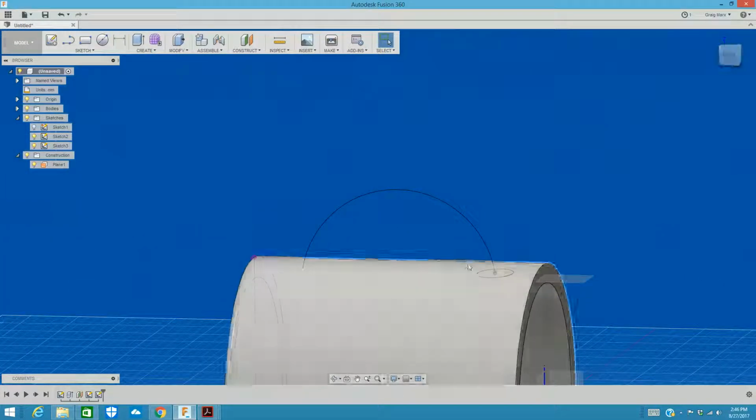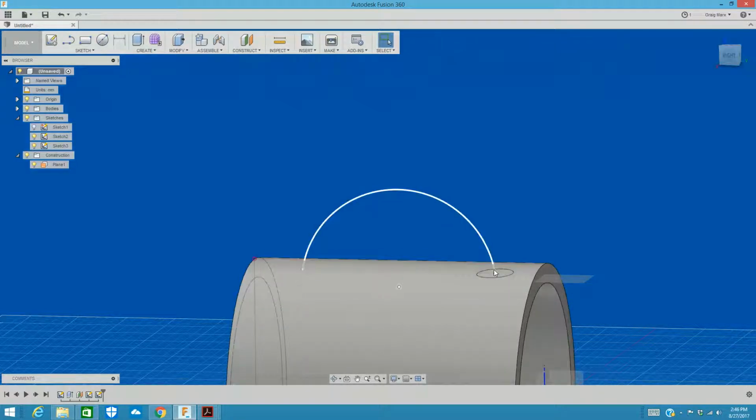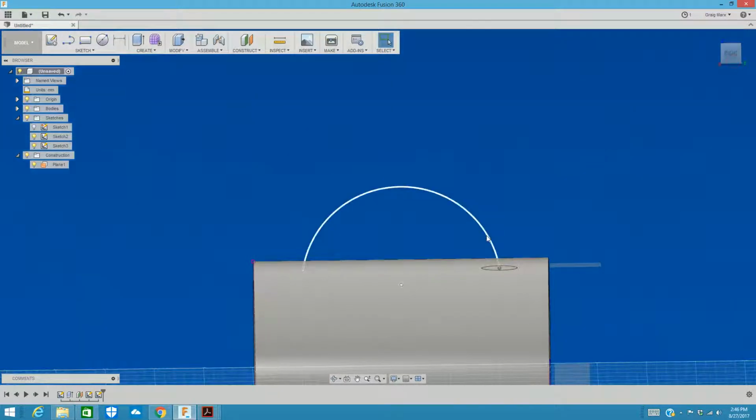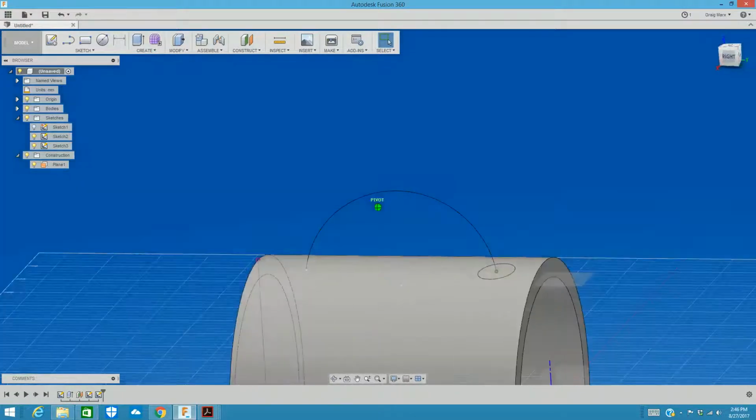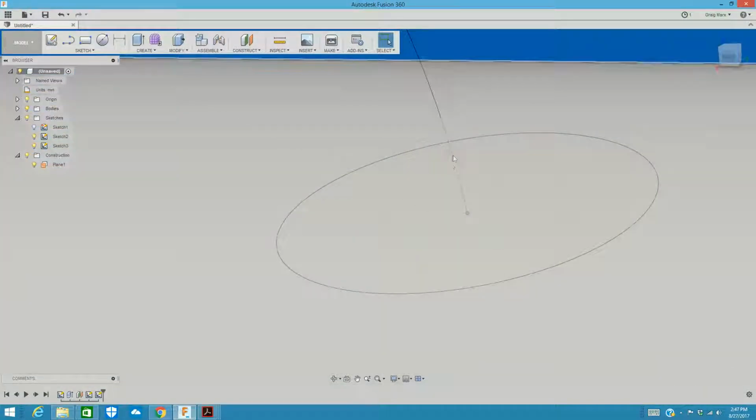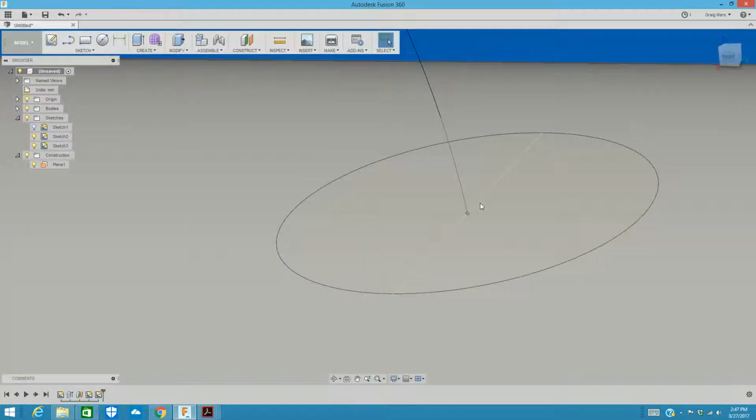And this is what I want to try to highlight. I have one sketch that I'm hovering my mouse over. That is the cross section of the part that I want to three-dimensionally pull or push. In a perpendicular plane, I have the path that it is going to take. So again, if I zoom in on these, between the path and the shape that I'm going to sweep, those are on perpendicular planes. If I can't pick those planes from the origin, I can go under the construct toolbar and find a way to move some planes around. You saw the offset plane tool being used.